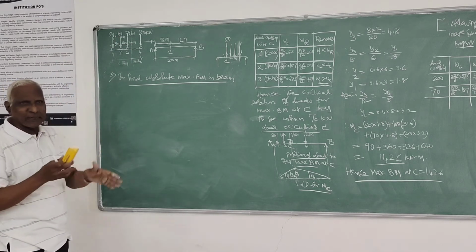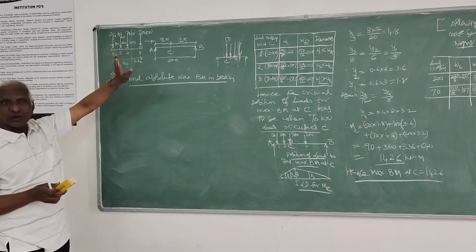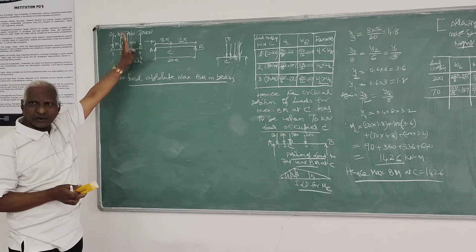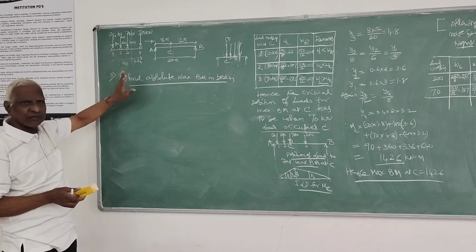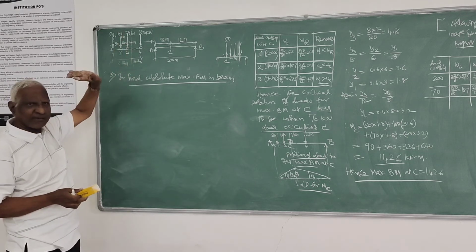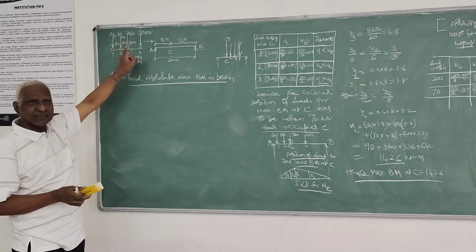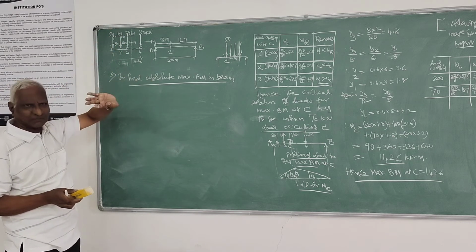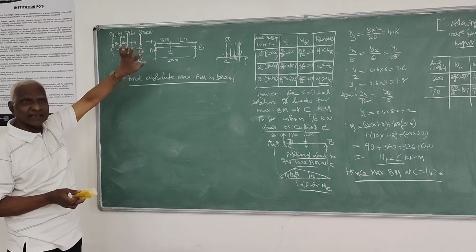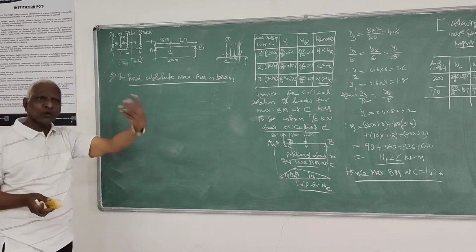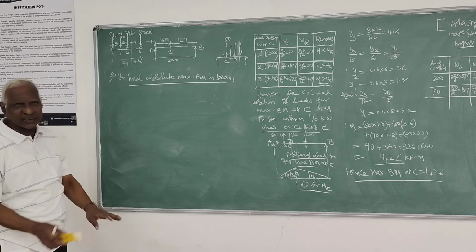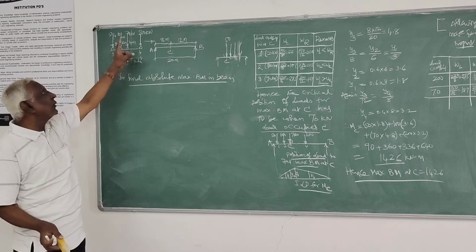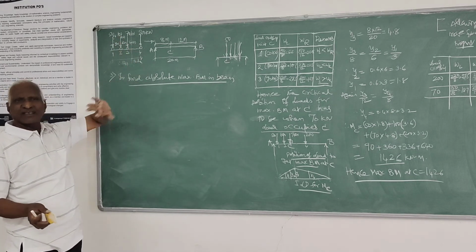So we have a dilemma now. Out of these two close loads, under which load? First, you have to select the loads which are very close to the CG line, the center of the load line. There are two loads; one is very large, the other relatively smaller. If they are of the same magnitude, you can take the closest one and one calculation will do. But in the procedure I have told, you can do the calculation for both loads, which lie on either side.